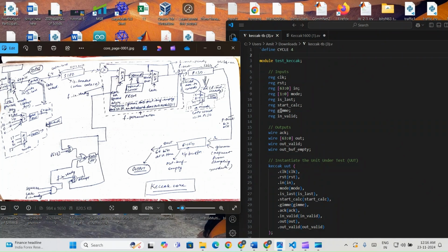This code would also be usable for others because it takes a systematic approach which makes it reusable and adaptable. For example, parameters like cycle can be adjusted for different clock periods. Additional modes or data patterns can be easily integrated. Waveform dumps enable post-simulation debugging, making life easier for the users furthermore.